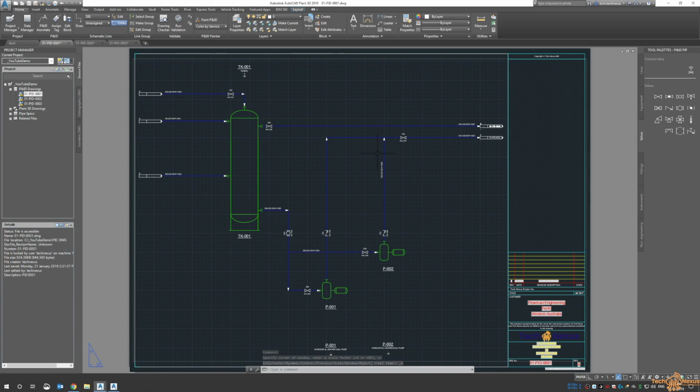Now, it's not going to stop you from doing structure or equipment, so you could set those models out, but before you do any piping, you have to do what's called a spec, which comes from a catalog. Plant 3D ships with 3 or 4 different catalogs out of the box, but if you want more of them within the Plant 3D software, if you look up at the top right where you log in, there's a little shopping cart icon. That takes you to the App Store.